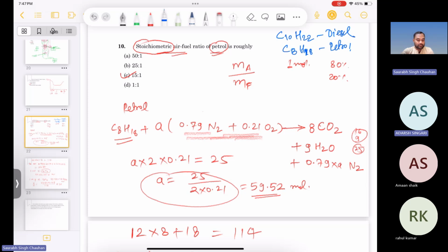Sir, what do you call this formula? I forgot the name. I think Dulong formula. Let me check. Dulong. So the Dulong formula is used for finding what? Calorific value, right? If a formula type question is given, we apply this formula. Well, this formula is like an empirical relation, an empirical formula, using a lot of fuels and their calorific values. So this is a rough estimate. You will not always get the correct value.